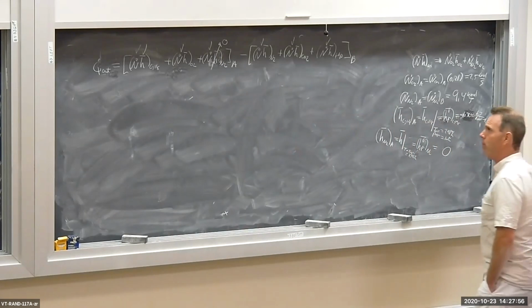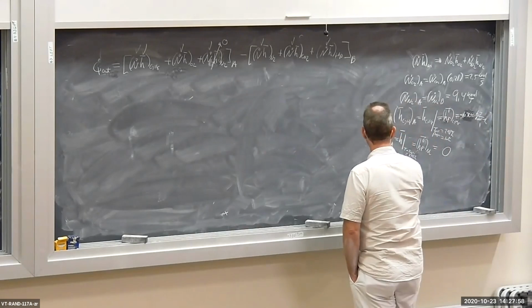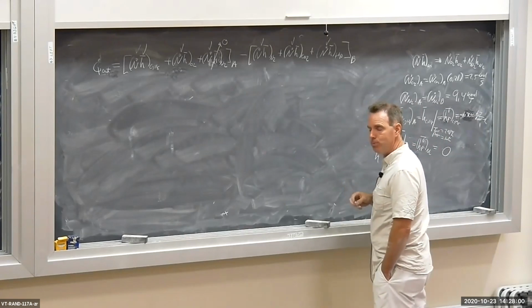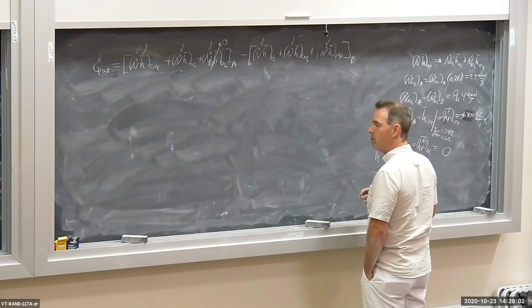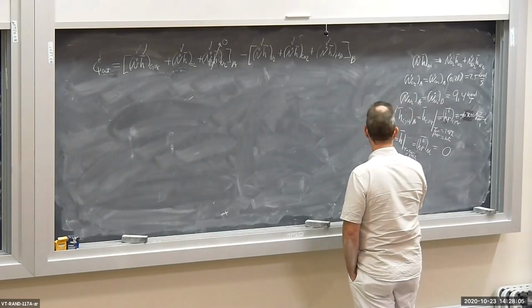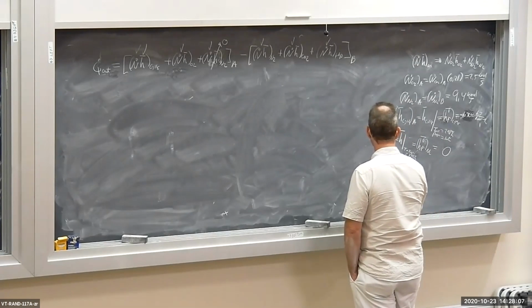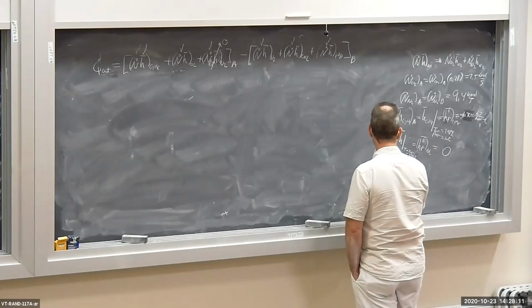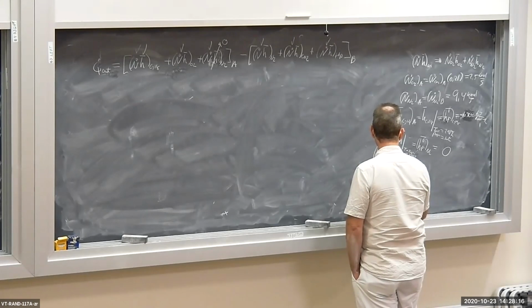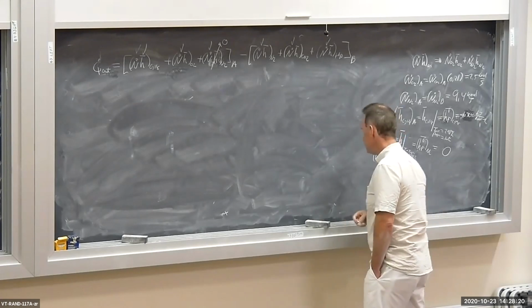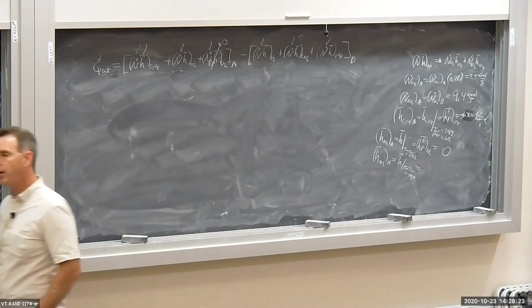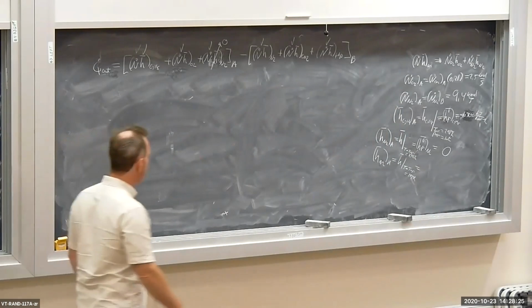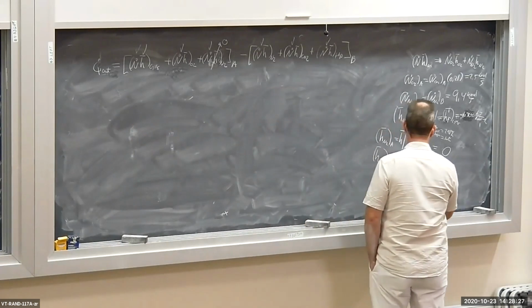What about the enthalpy of formation for the O2? Specific enthalpy of the O2 at the reactant side, H O2 bar, is equal to H bar evaluated at T equals Tref, 298 Kelvin.